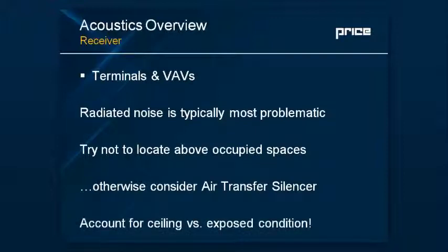And again, we're seeing more and more designs where architects are not using finished ceilings. So it's good to point that out, because AHRI and other standards typically account for some sort of ceiling effect, which ultimately reduces the noise. So when you have an exposed condition, you're going to potentially have some noise issues because you're not getting that attenuation.